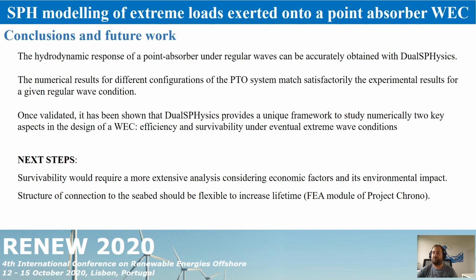The hydrodynamic response of a point absorber under regular waves can be accurately obtained with DualSPHysics. We have validated numerical results for different configurations of the PTO system for a given regular wave condition, and once the tool has been validated, we have applied it to an efficiency and survivability study, survivability under extreme wave conditions using a focused wave. Our next steps will be to do a survivability study, including also economic factors or environmental impact.